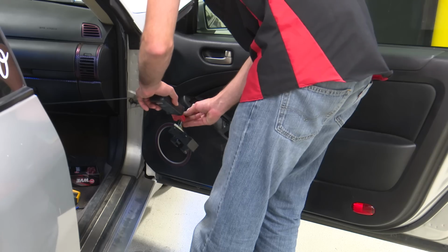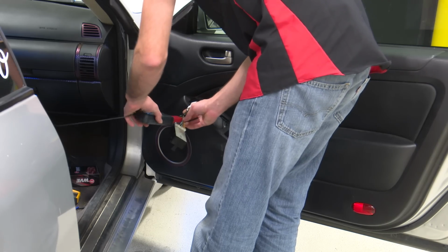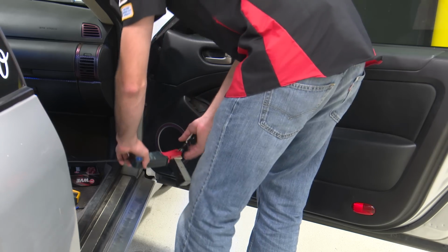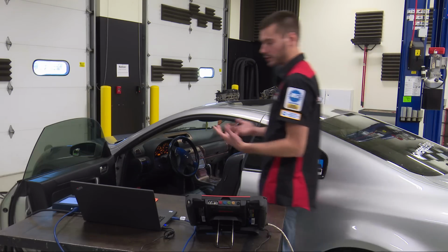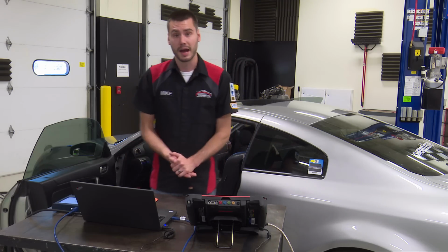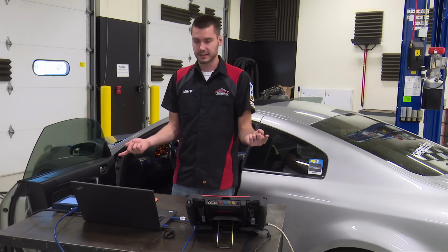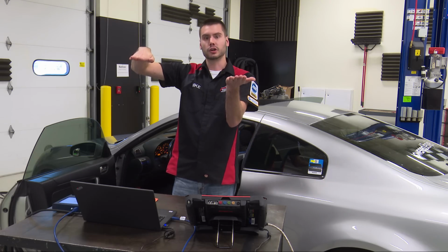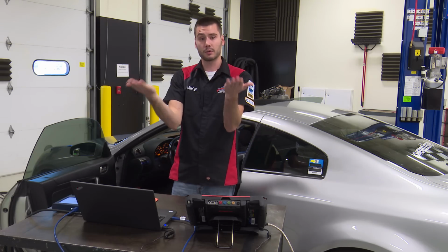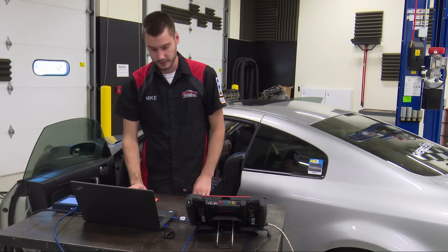So for starters here, I'm making sure my clamps are in the same direction. Both of my clamps currently have the writing on the clamp facing away from the switch, so they're both going to read current in the same direction. That way we get a similar looking pattern for both, okay? If we put one clamp facing this way and the other clamp this way, the current is going to go in opposite directions. So right now we have both clamps facing the same way.